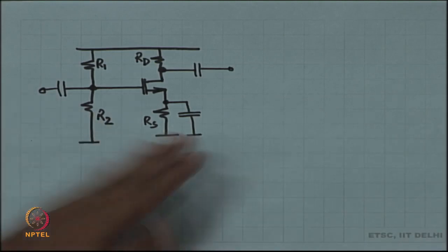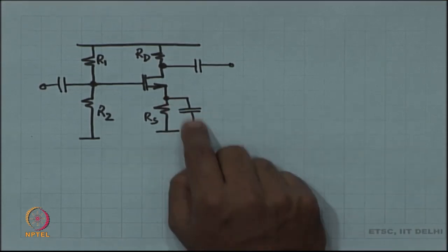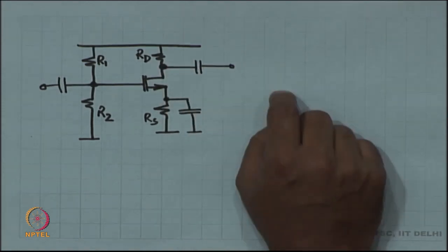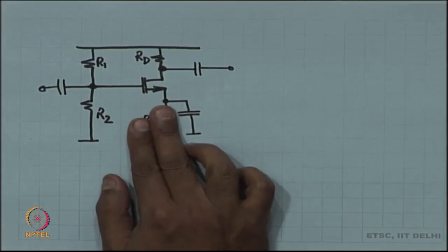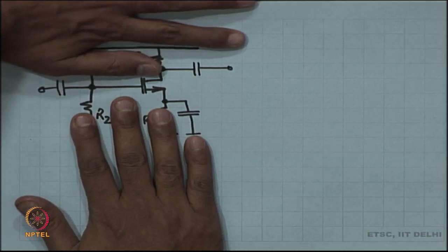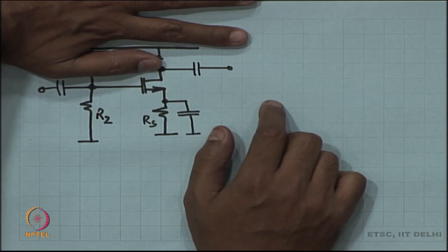How do you quickly think about the gain of this structure? Very quickly, you do the Norton equivalent, right? Try to do it in your mind. This is a short circuit. So, experiment 1 for the Norton equivalent is to do the short circuit test. I do a short circuit over here. So, RD does not matter, RS never mattered anyway, R1 and R2 never really matter, right. So, I apply a signal at the input. What is the current in the short circuit?